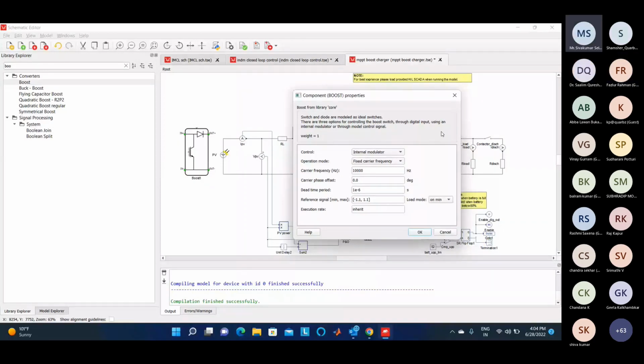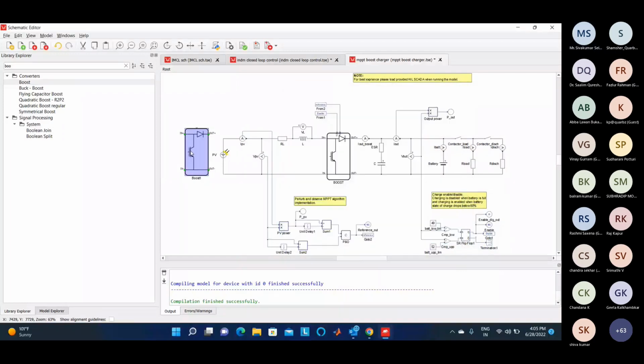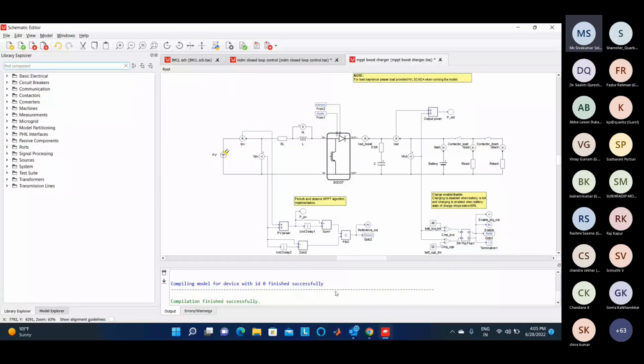In the morning, you showed a demo of C code generation in MATLAB and interfacing it with the Typhoon using an advanced C function. But I have a doubt. Suppose I have multiple DC to DC converters with solar PV panels. The way I control the DC to DC converter with the MPPT is going to be the same, so I cannot generate three different algorithms from MATLAB. The algorithm is the same. How can I use multiple instances of the advanced C function within a single schematic?